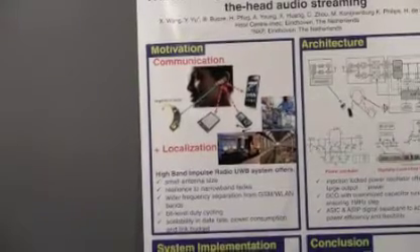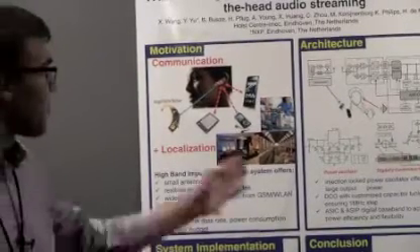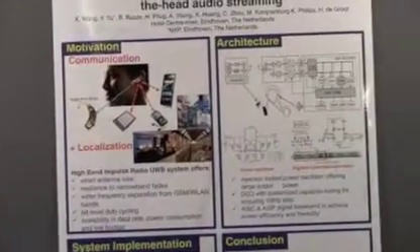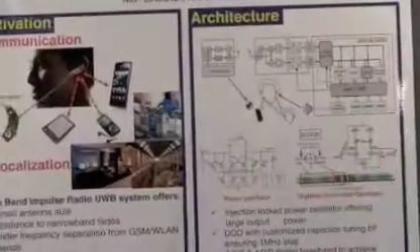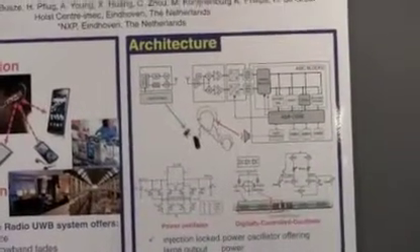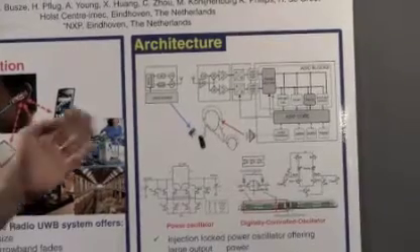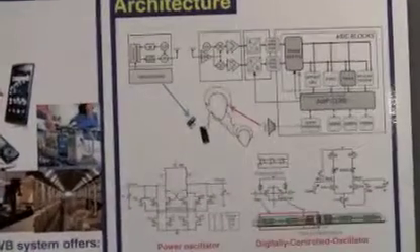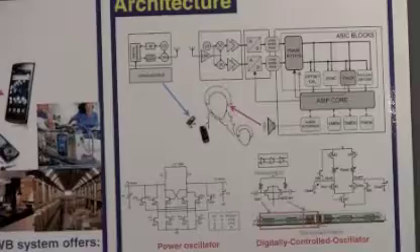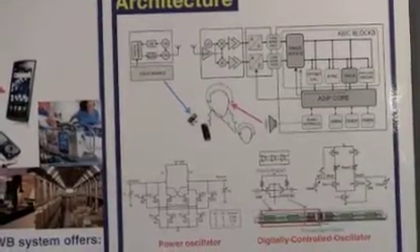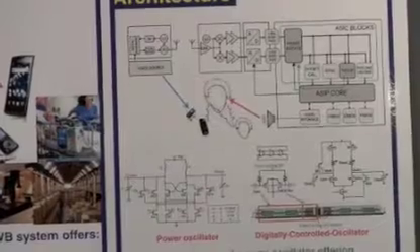So how does the architecture look? We have a transmitter and a receiver setup. The transmitter is a complete integrated chipset. It contains the digital baseband and the analog front end. On the receiver side, we have the analog front end as a separate chip, the A to D converter as a separate chip, and the digital baseband, which is mapped on an FPGA platform.